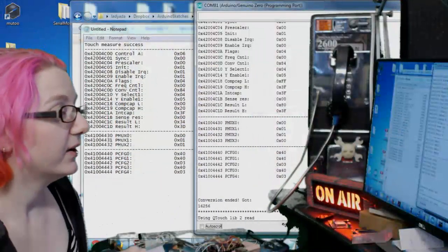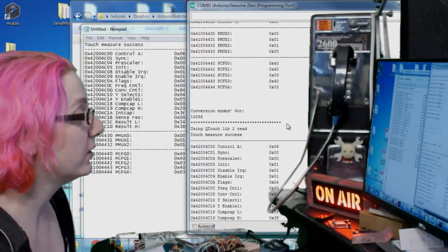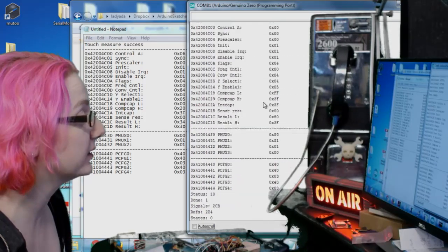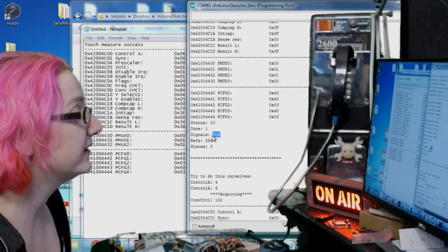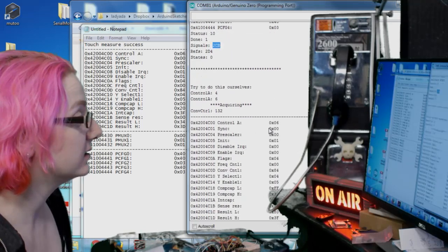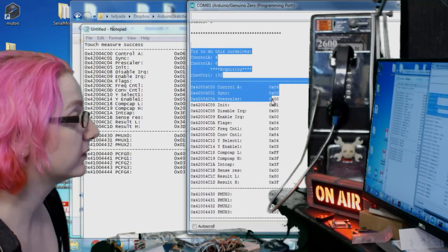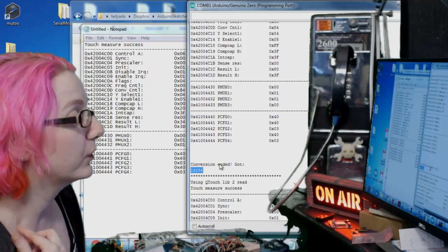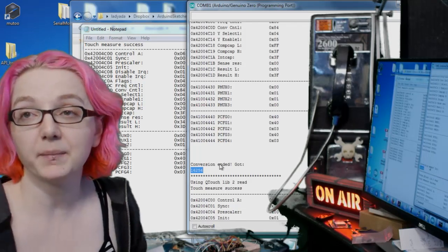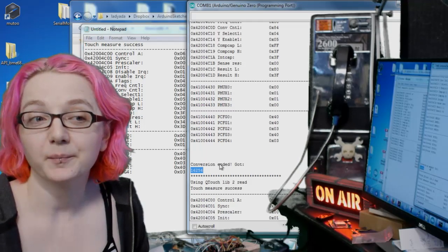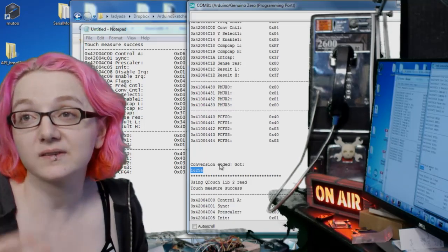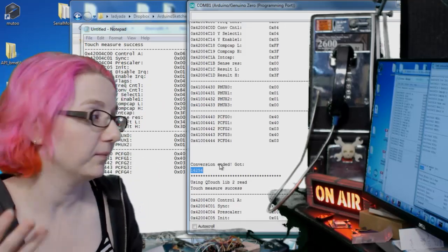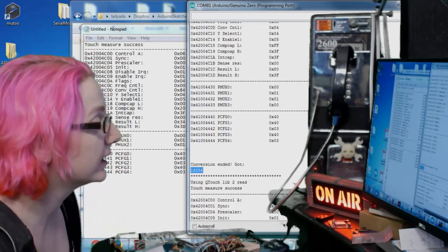Nice. Okay, so we're back. So the QTOUCH library gets us these signals. And then when I do this myself, this is my code that's running, I get these big numbers. Now, one of the reasons I'm getting big numbers is I'm not dividing by 16. What the library does is it takes those 16 samples, like all those little notches you saw, and then divides by 16. I'm not doing that because, again, I can always do that later.